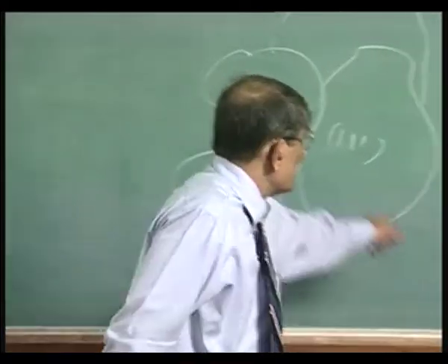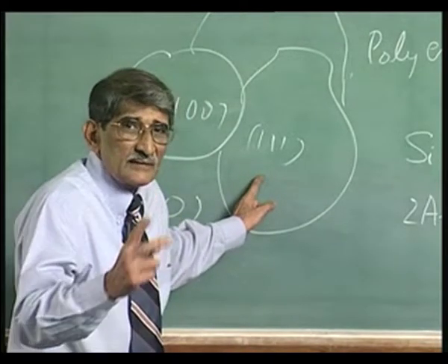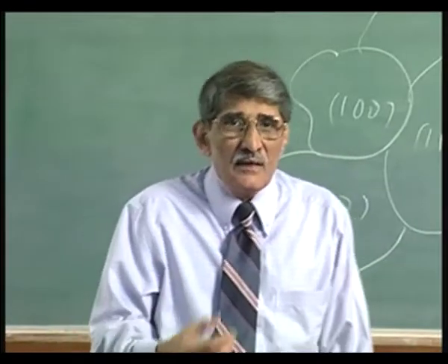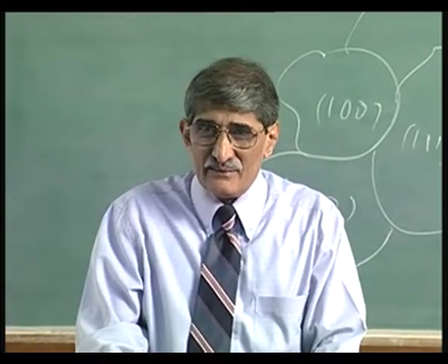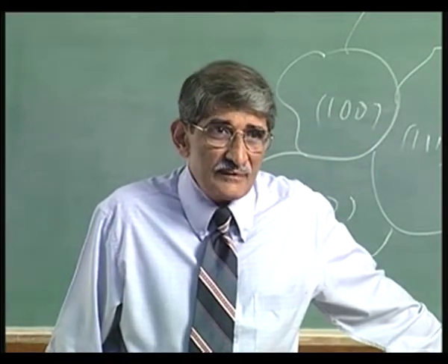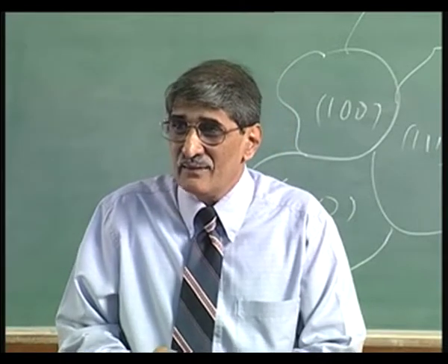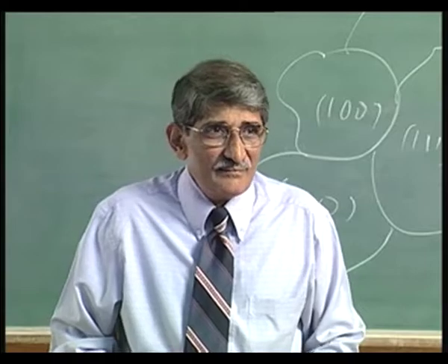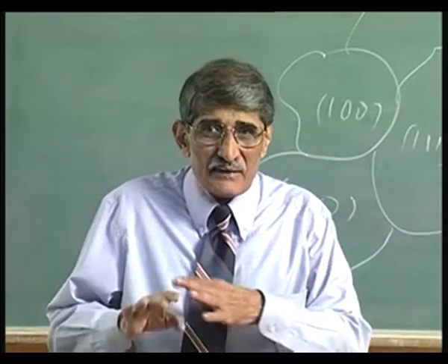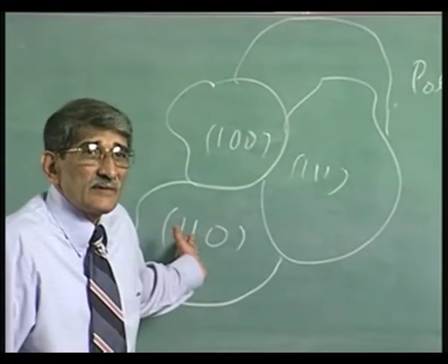Now, in silicon, that poly you obtain there is due to two factors. One is temperature, about 625 degrees centigrade in the MOS technology. Two, you grow it on oxide. You deposit on oxide, both put together you get polycrystalline at 625. You lower the temperature down to 550 degrees centigrade, you will get amorphous silicon there. Okay. So, it all depends how much energy it has to move around. At least some degree of orientation you get if the temperature is 625.